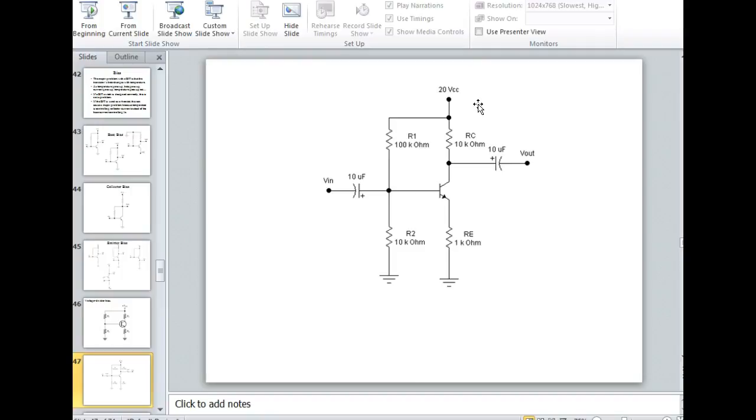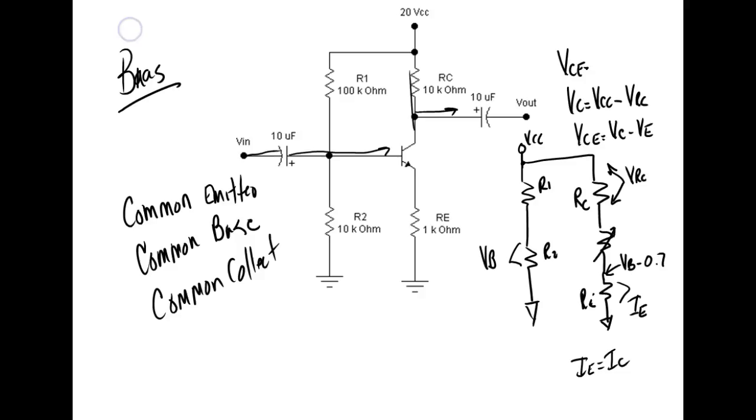Now, if we load this thing, so this guy's going to hook up to something, right? Y'all understand that? And as soon as we hook up to a load, what would you expect the gain to do? Would you expect it to go up or go down? Down. So let me bring up the PowerPoint. Now, the output of the circuit is generated right there.